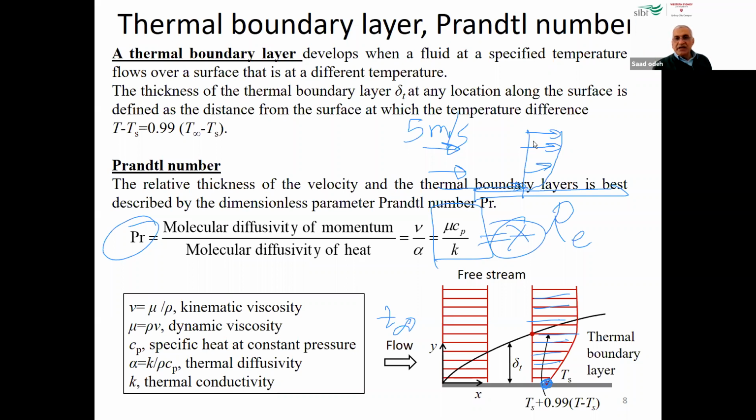But again, those who don't have any idea, you just follow the definition of each equation. For example, for this Prandtl number equation, just follow this definition. Here, nu is kinematic viscosity. You can get this value from tables. Even dynamic viscosity, same thing, from tables, based on the fluid. Specific heat from tables, k from tables, all these from tables. So all you need to know is the temperature and the fluid type, and then you go to tables, find these values, and substitute them in the equation.